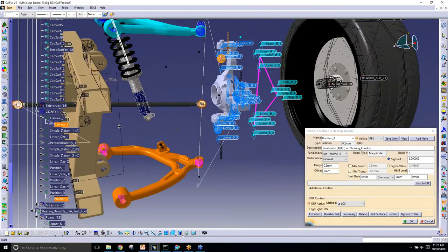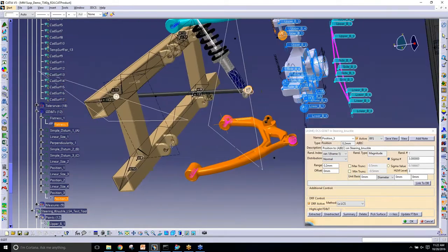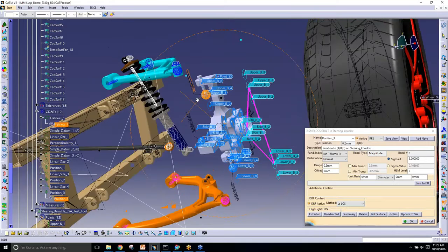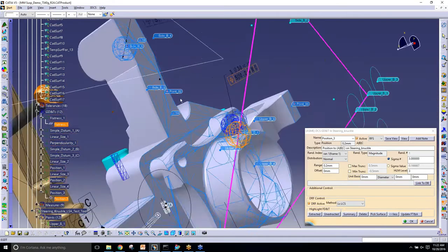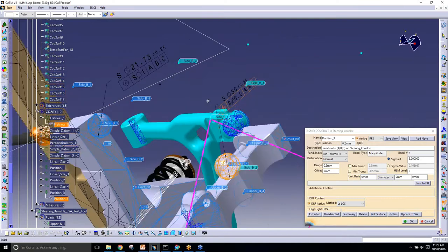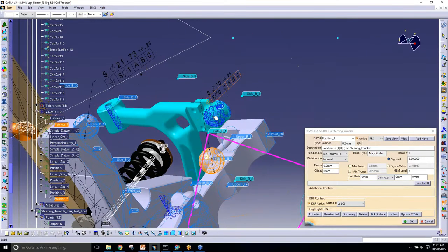So basically, you can change all the tolerances in 3DCS that you pulled from the GD&T in CAD, because this works for PMI and NX as well. You can test it, so you can make multiple changes in 3DCS, test and optimize before you push back into the CAD. Right. So really, 3DCS becomes a test bed for optimizing your GD&T. Yes.